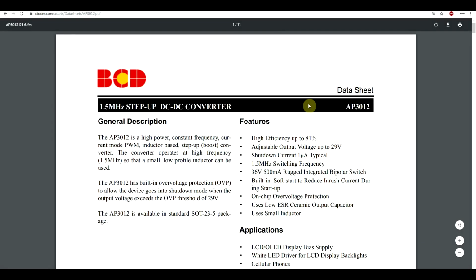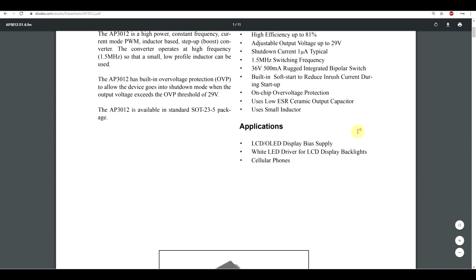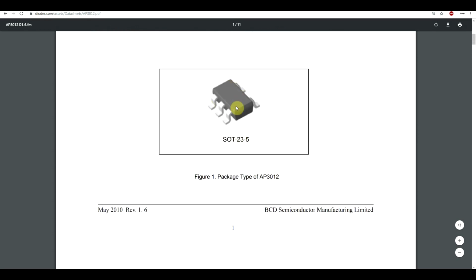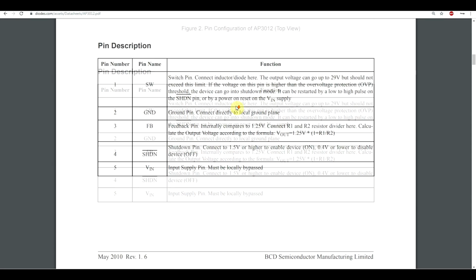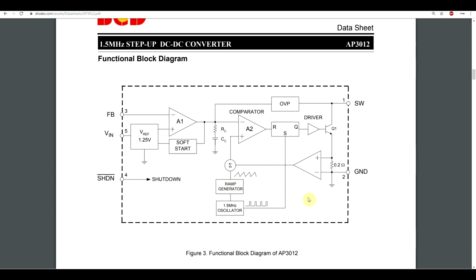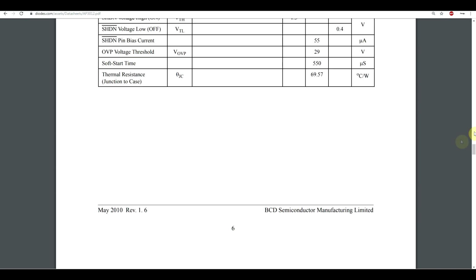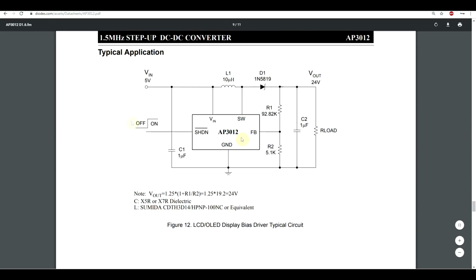I would like to start this electronics tutorial off by saying that this is the power supply that I'm actually using. This is a tiny little IC, and the reason why I chose this is because it's so small and so compact. Most of the things needed to build a power supply, like oscillator, reference, compensation, everything is integrated. Even the switch is inside. If you want to build a boost circuit with this thing, you just need a handful of components. But there's a drawback, of course.